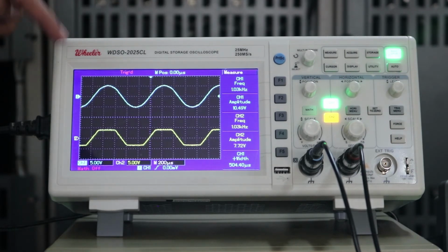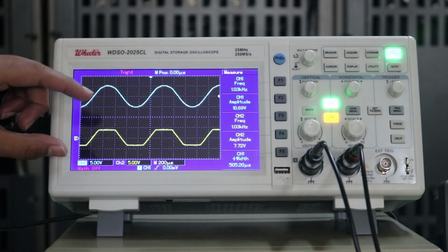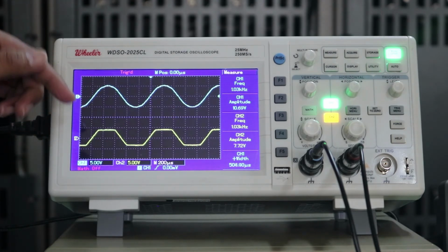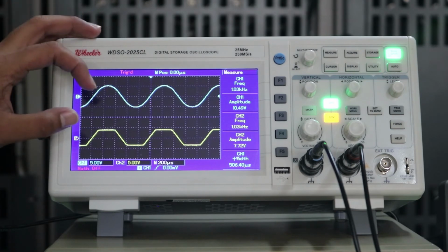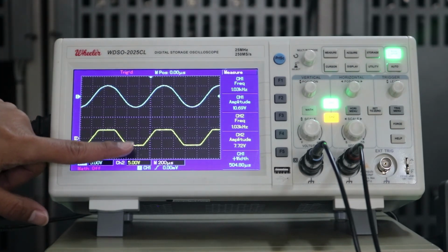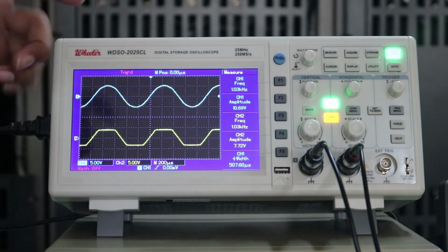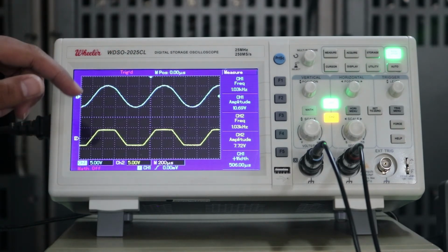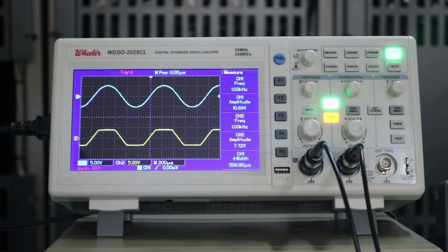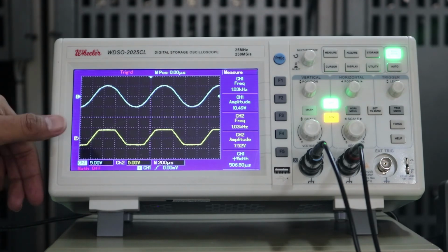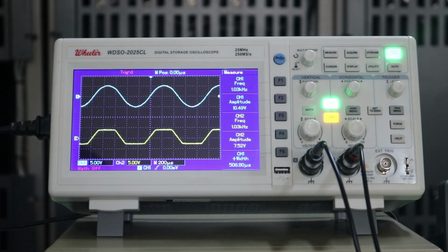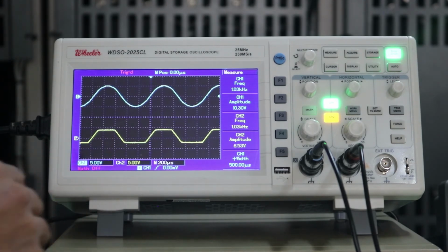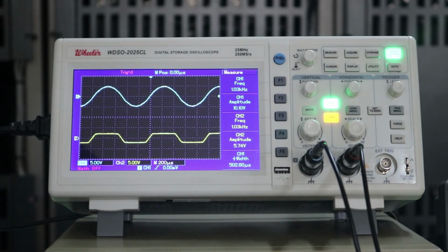As you can see now, from our input waveform, both parts of our cycle have been removed. The positive cycle has been clipped, and the negative cycle has been clipped. So the portion of the clipped signal depends on the amount of voltage from our external voltage supplies. As I adjust the voltage supplies, you can notice the changes in our output waveform. So you see, to the negative, then to the positive. And that's the output of our dual clipper.